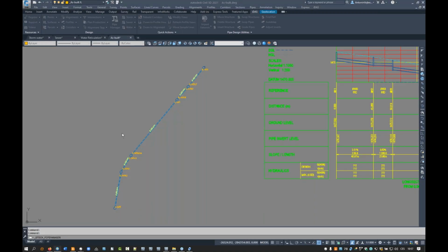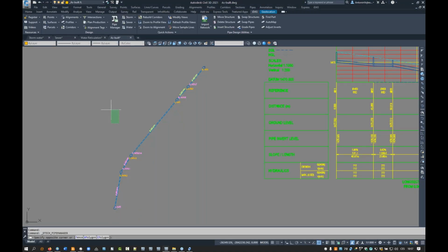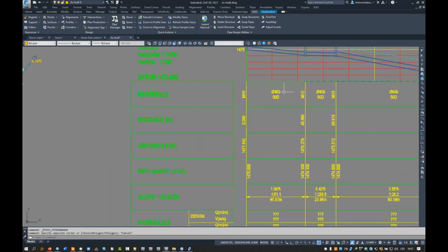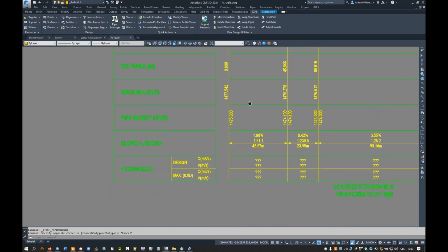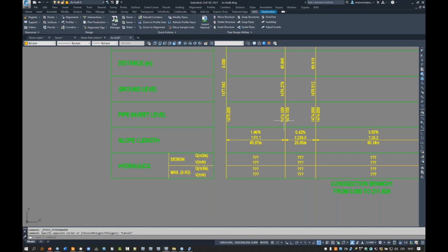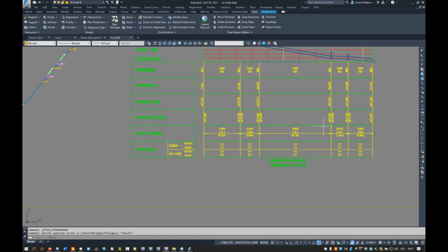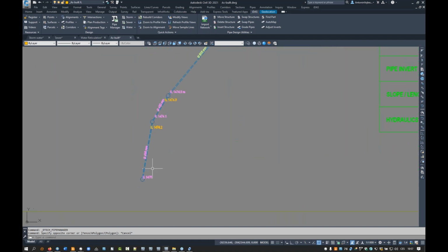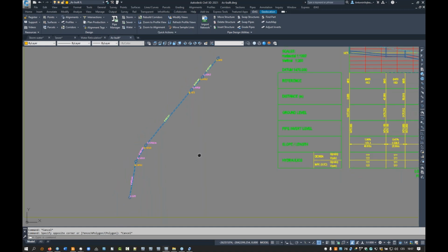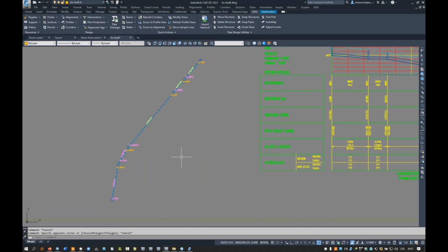Update, so it's updating. So the first two pipes are swapped to 450, and the start invert elevations are applied, not the end invert elevation. And if the text was processed, it is moved to processed invert elevation or processed diameter. So you know those pink text values were processed, they were used; orange were not used, green were not used. So you can quickly check what text were used and what not.